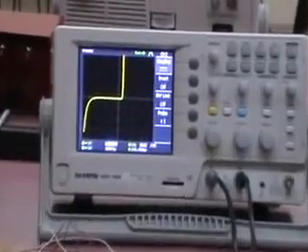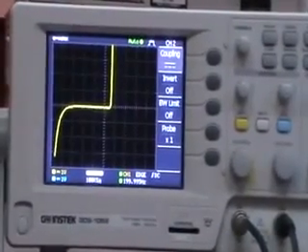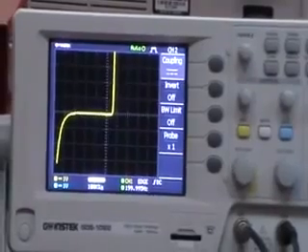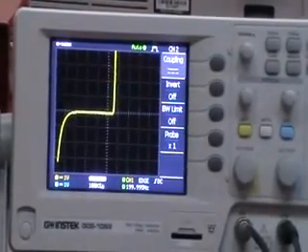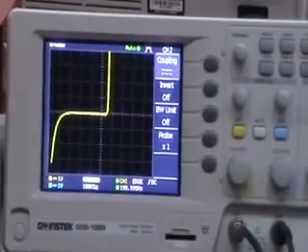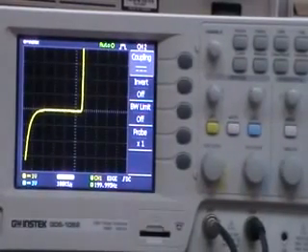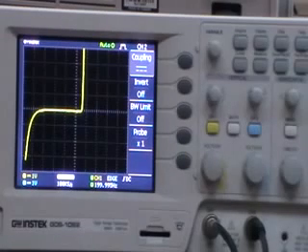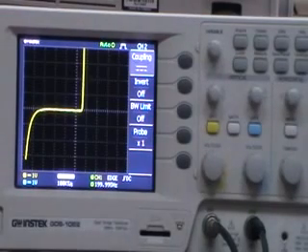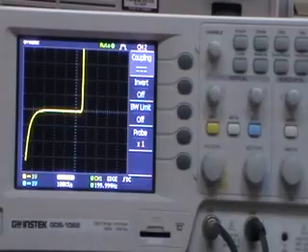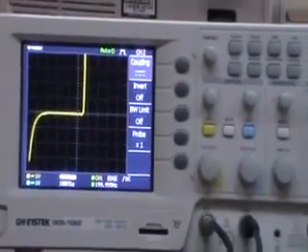The Zener diode in the forward bias case, or in the first quadrant, acts similarly to a general diode. In the reverse bias case, it has a breakdown voltage where the reverse saturation current suddenly increases. So repeat all the steps that we have done previously, and in the last step, along with finding the knee voltage, we should find the Zener breakdown voltage. The Zener breakdown voltage is shown in the diagram in the manual, that is the peak inverse voltage.